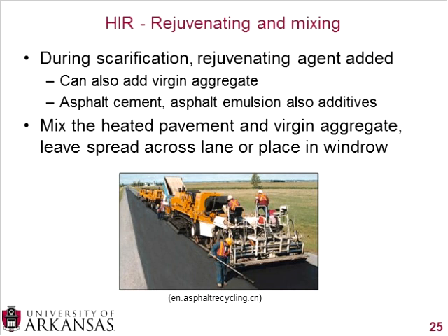While you are scarifying or milling, you can add either your rejuvenating agent, virgin aggregate, and also your asphalt cement or your asphalt emulsions. One of the dangers of adding asphalt cement is that if that temperature starts dropping too much, you can start having compaction problems. So that is why asphalt emulsion is a pretty popular alternative, because you still get that lubrication for the compaction, so you can get your density at the very last step.